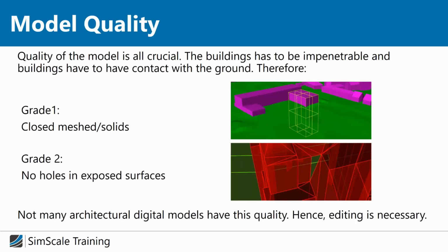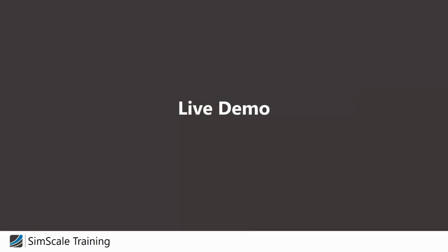The quality of the meshes is preferably a closed mesh, but the SimScale platform can use open meshes as long as you don't have exposed holes in your surface. If you have holes, then they need to be hidden from your computational domain. So, to you, Milad.